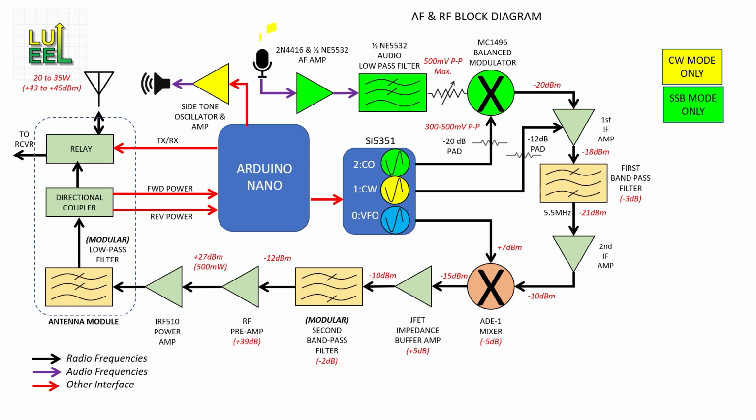Here's the block diagram: a mic preamp, a low-pass filter section, and then the balance modulator. The issue is there's no automatic gain control in this section. All that I have is a potentiometer here at the input to the balance modulator to adjust the audio level. And not having AGC meant that I constantly struggled getting full dynamic range from my spoken voice.